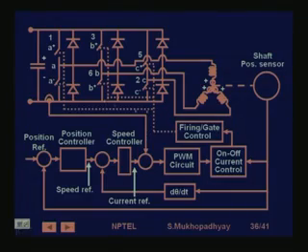So now, based on the current reference, there is a PWM circuit which will switch this inverter to maintain a certain amount of current, and that current maintaining strategy is very much like our micro stepping strategy, that whenever the current reaches the limit, we will switch off. We have seen how we can do this torque control in the case of other AC motors also using an inverter. So exactly similar current control is also applied here.